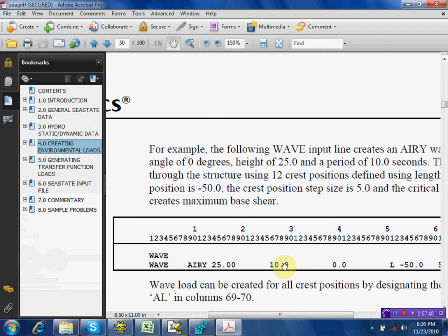We have a project in Total Indonesia. It's an eight-legged platform. The top side is heavy. You cannot lift, you cannot use a trailer. So what we did is skid shoe, just like jacket skidding. You put winch, skidded, two barges. For heavy lift.